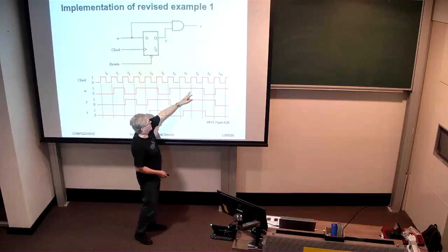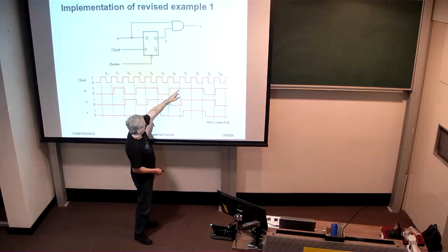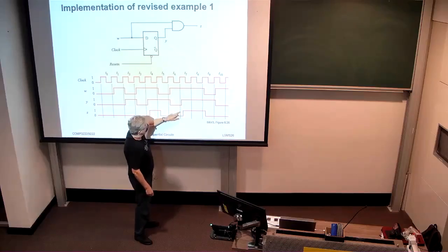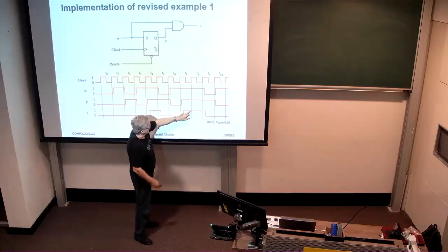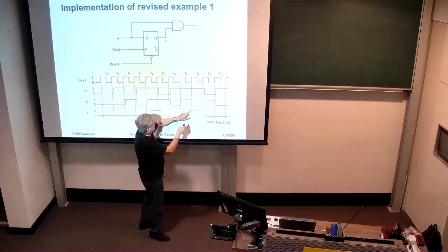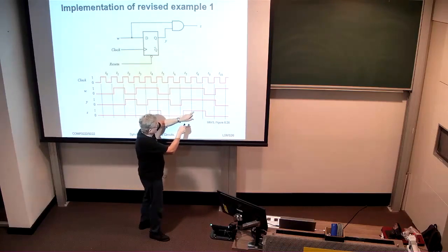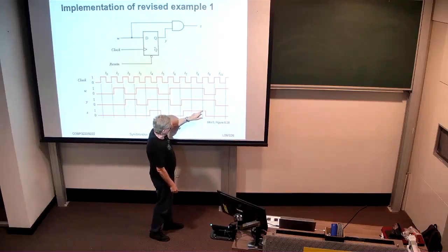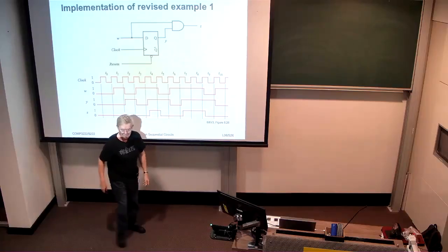Here we see then 3 successive ones in a row whereby the first rising clock edge gives rise to the flip-flop going to 1, then the output goes 1. The next rising clock edge, input still high, flip-flop's high, output doesn't change. Next rising clock edge, input's high, the flip-flop's high for the next clock period, but the output goes low as soon as the input goes low.